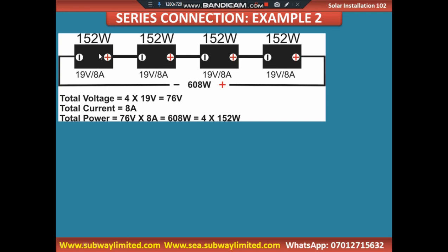So if we have 4 solar panels and each is rated 19 volts, if we connect them in series, you will have 4 times 19, which is equivalent to saying 19 plus 19 plus 19.